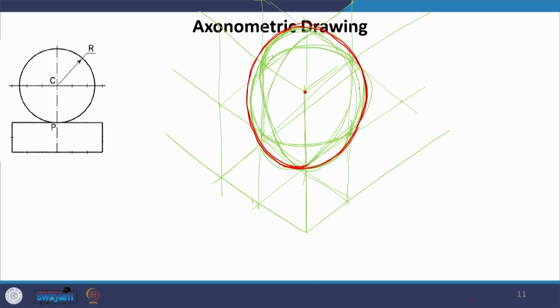Okay. So, the only thing being that we can't directly derive the radius. In isometric we were using the isometric scale. So, if we were using the isometric scale, the true dimension of the sphere was what was seen in isometric view if we were using isometric scale, or it was scaled up to 1.2 times. The same would happen here in axonometric scale, and we will see a bigger circle representing the sphere. Okay. So, that is what we are going to see in axonometric too, and I will stop here at this,